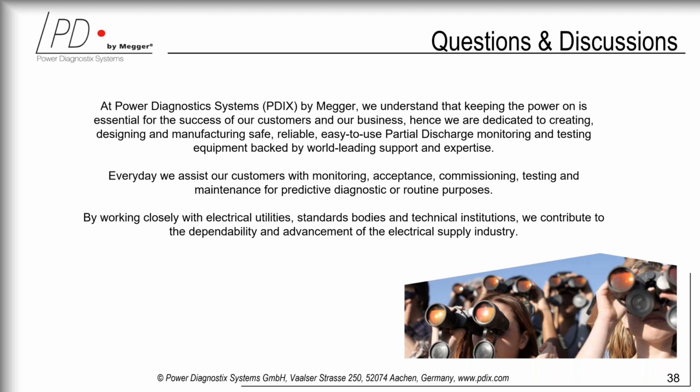Generally speaking, transformer factories or power utilities that buy new transformers will install monitors right from the get-go. People that have had transformers in action for a long time, and I think in the US and Canada this is the case, with transformers there for 30, 40 years, are a prime example where a monitoring device should go, because at any time we can catch early partial discharge and avoid any catastrophic failure.